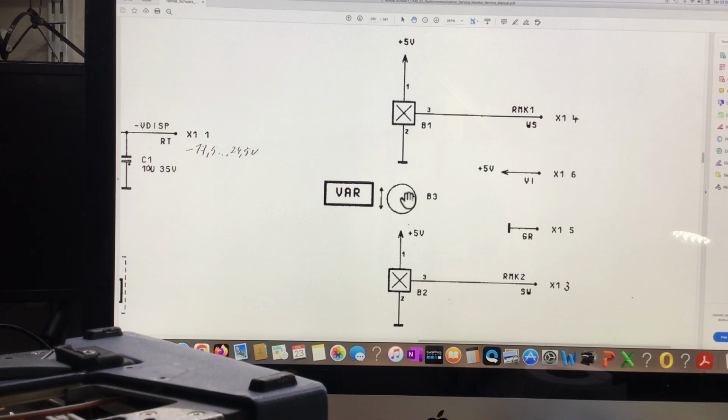And so I think, although it says there are 12 north poles and south poles, I think there's a total of 24 detents in the disc. So each notch would mean that each sensor would measure both a north and a south pole, and thus when we turn the control clockwise, the pulse train being measured by the digital circuitry would represent a clockwise motion, and when we turn it anti-clockwise, then naturally that pulse train will essentially reverse in the opposite direction. So this is where it talks about that 90 degrees out of phase.